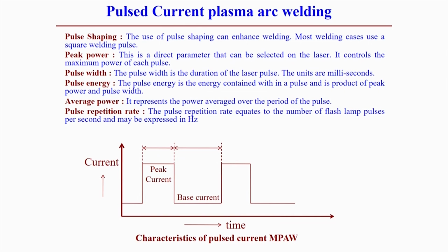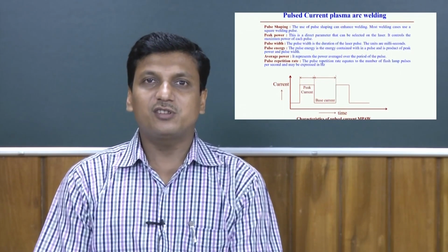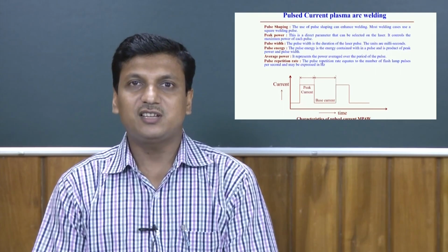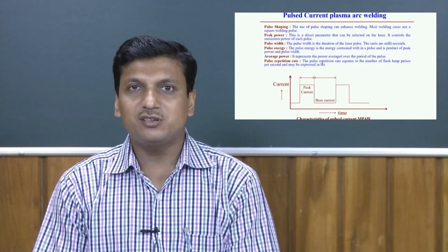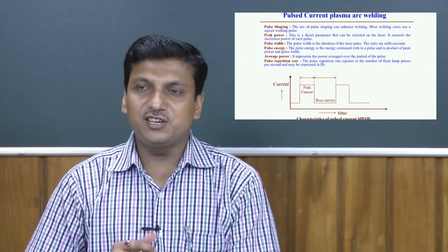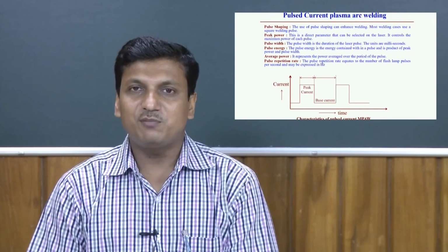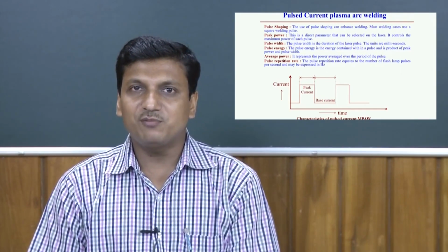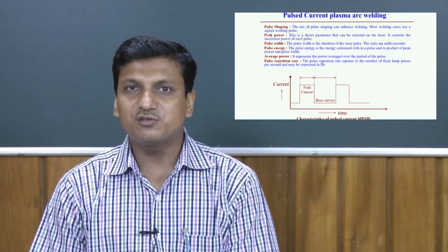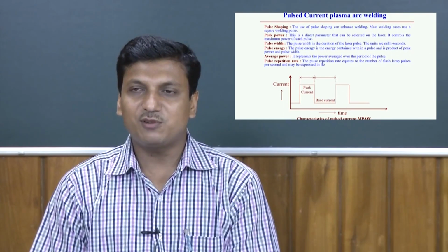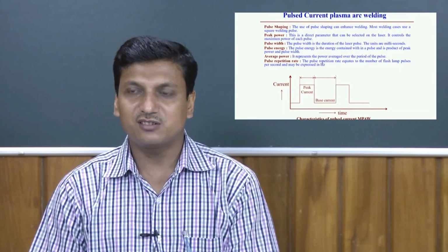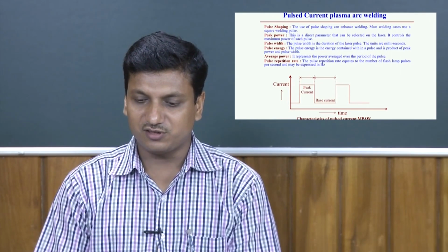The purpose of using pulsation even for plasma microwelding processes is that it helps to join very thin sheet applications. Basically, the ramping of the power in this case helps to join even much smaller thicknesses of material. That is the purpose of pulsation even in the plasma microwelding process.